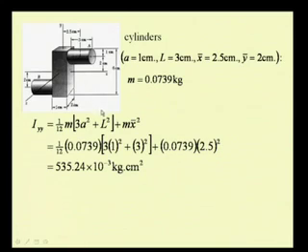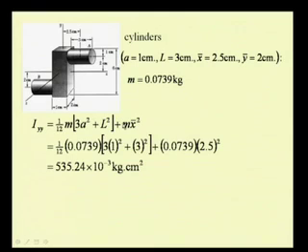If you remember, in the last lecture we tabulated these values, plus mass times x bar square, that is the location of this centroid with respect to this yz plane along the x axis, which in this case is 2.5 centimeters.